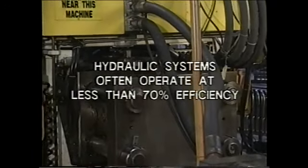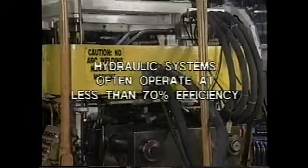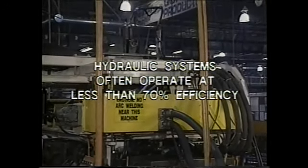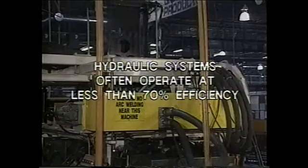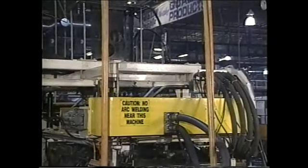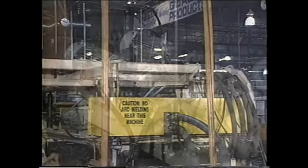The energy lost due to friction prevents any hydraulic system from operating at 100% efficiency. Often, an industrial hydraulic system will operate at less than 70% efficiency. That means if we put in 10 horsepower, we get out less than 7, with most of the missing 3 horsepower having been lost to friction throughout the system.